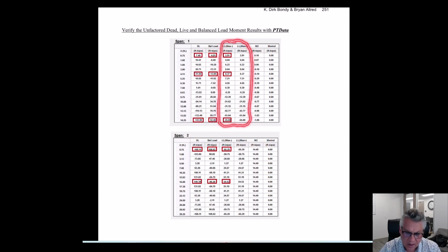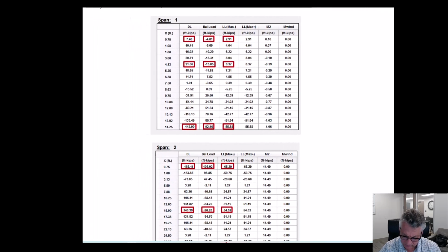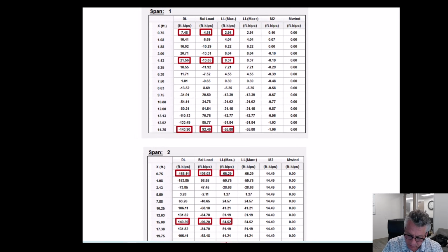You have to have very high live loads to have the code kick in a requirement that you skip those loads. So because the panels are so large, it's assumed good enough if we just apply the uniform loads without skipping the live loads. So the live loads are going to be the same: max negative, max positive.